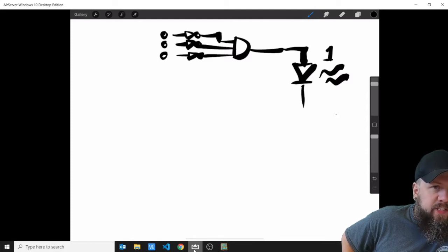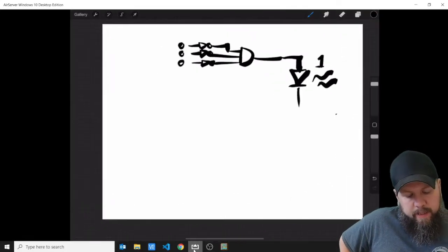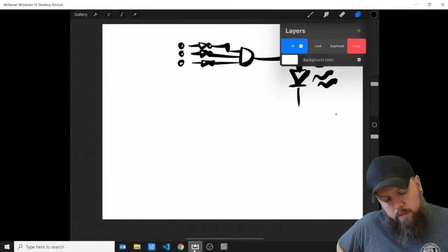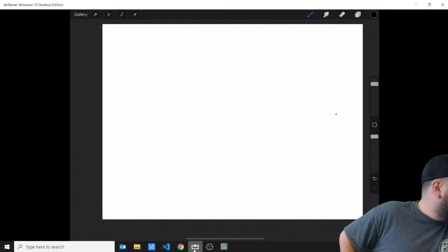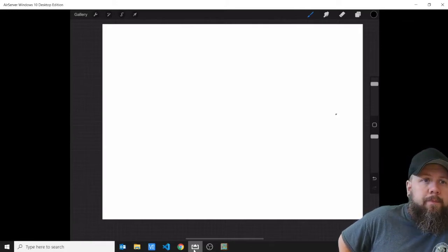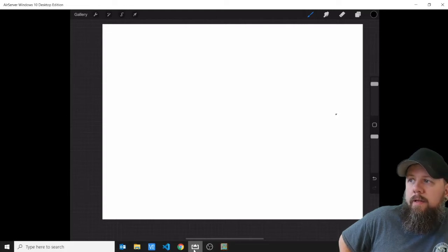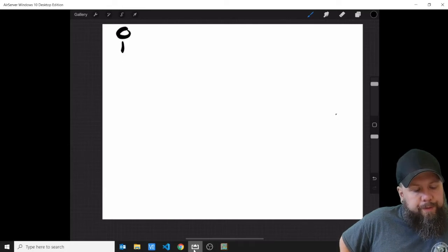So we need to go the opposite direction a little bit. We're going to make an encoder. They did one for 0 through 9, and they needed 4 bits to do that, because 8 and 9 you can't get into 3 bits. I don't want to do that many right now. So let's go 0, 1, 2, 3.